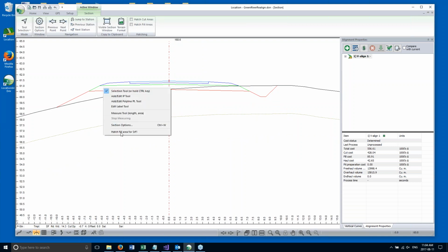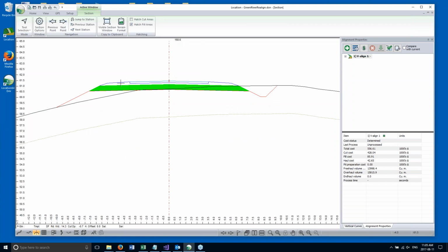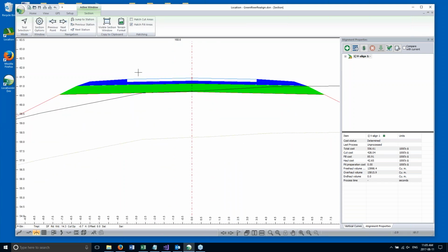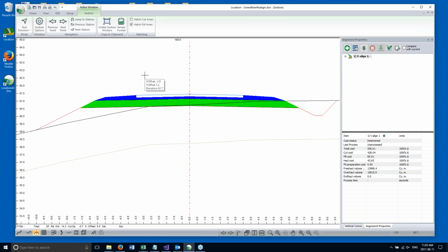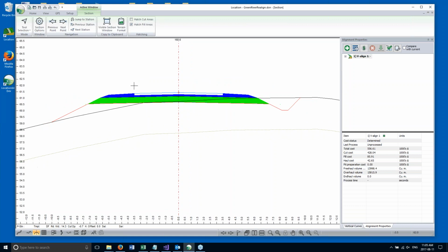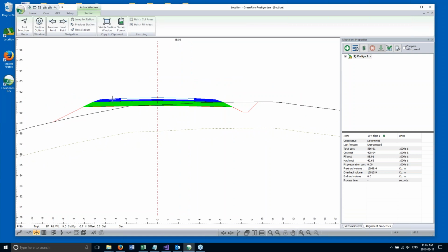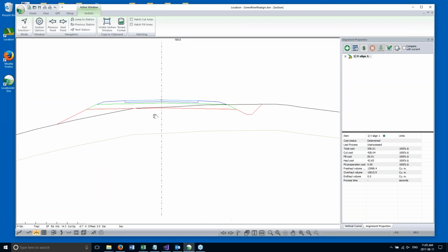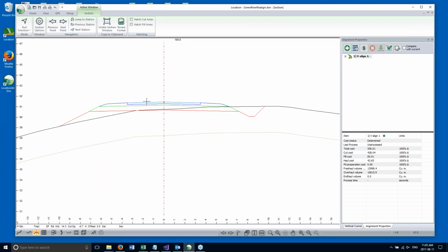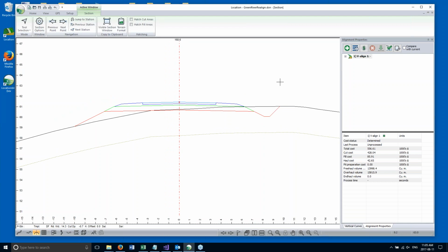You can see also there are layers above subgrade, various engineered materials that are being placed above the subgrade line. These are expensive materials, obviously, and you'll want to track them, particularly if you're changing the length of the road. But in terms of vertical alignment positioning, they don't have a lot of significance. They are often ignored when considering vertical alignment position. But again, they represent a very big cost, and they should be tracked.